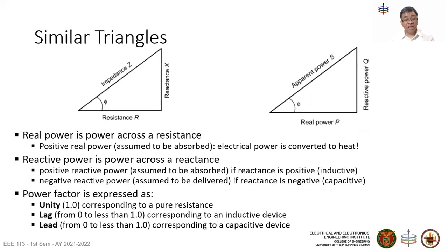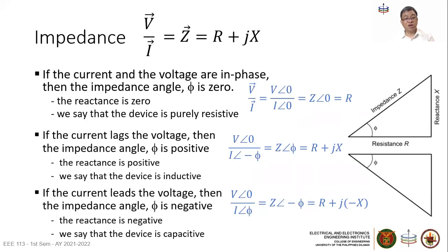Likewise, we have a leading power factor here corresponding to a capacitive device, where the current leads the voltage. Similar to what we had earlier, this case 3 here, current leads the voltage. We have a leading power factor for capacitive devices.